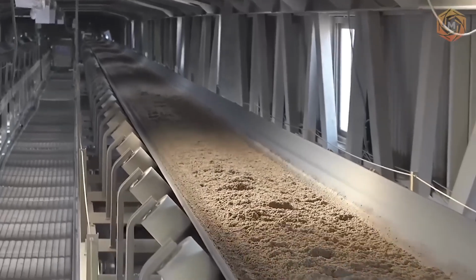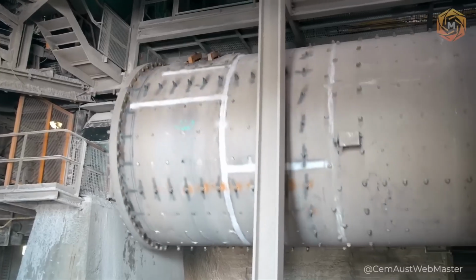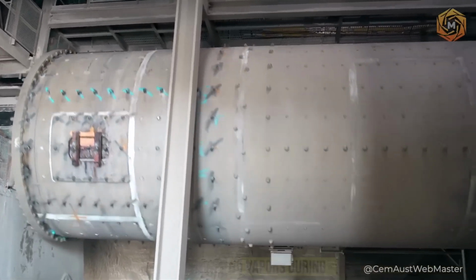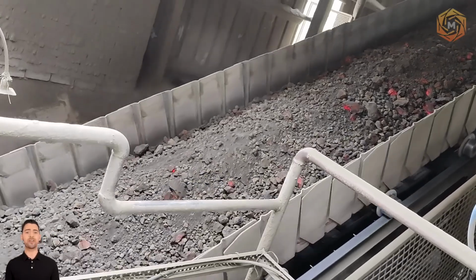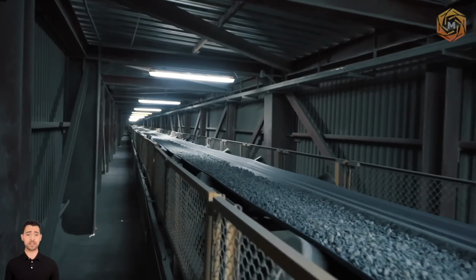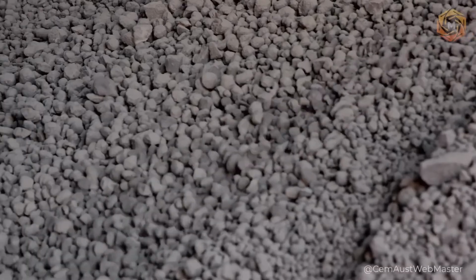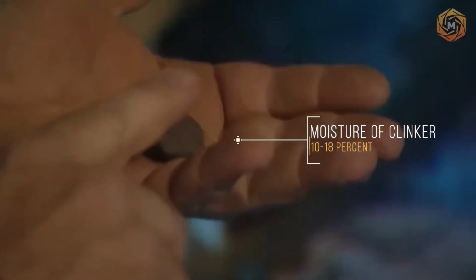What are the advantages of this technology? Firstly, the great thing is that heat inputs are significantly reduced, as there are practically no vapors during the firing process. As for the dry method, water is used in the process of pelletizing the finished mixture at the production facilities. However, its quantity is minimal. As a result, the moisture content of clinker that is moved into the kiln is about 10 to 18%.